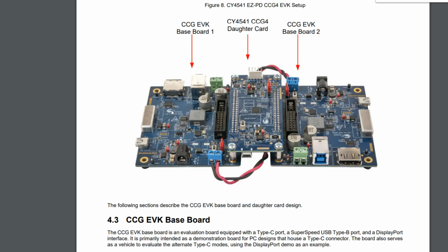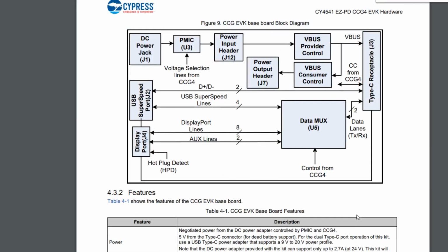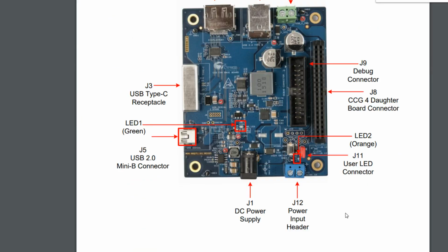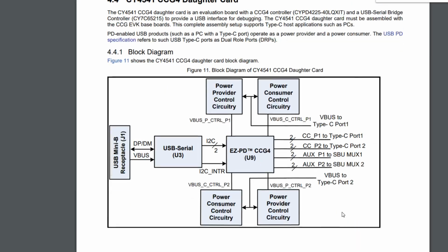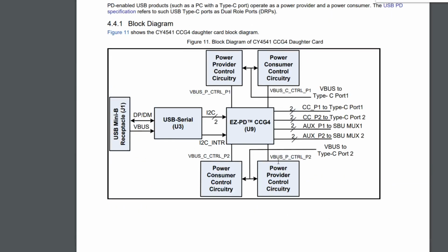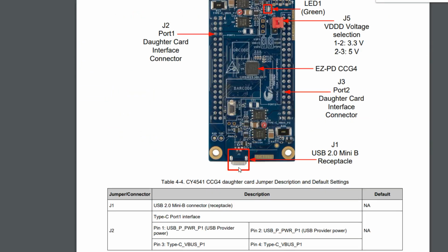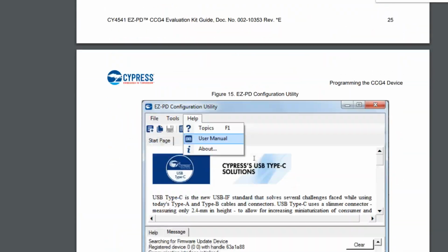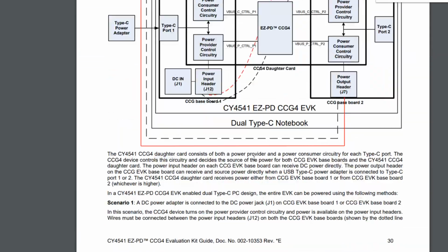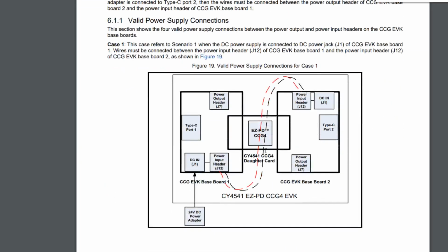Now here we have a buck connector. So on these pins, there's going to be between 15 to 20 volts. So let's talk about the case where you've plugged in a DC jack. Yeah, so here you've plugged in a DC jack, and they're assuming 24 volts. 24 volts goes into here.